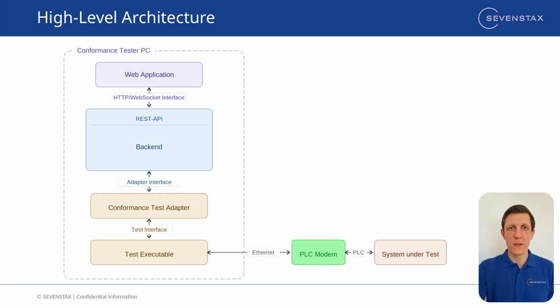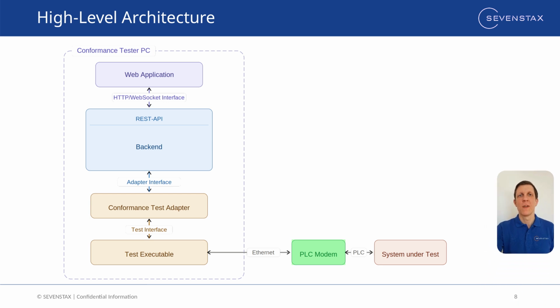And here we find the PLC modem again, our small black box from earlier. It acts as an interface connecting the laptop to the system under test, enabling the test executables to interact with your product via the control pilot line of a charging connector. This includes the low-level communication using CP state changes and PWM, as well as the high-level messages over PLC.